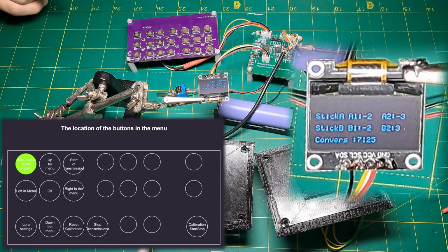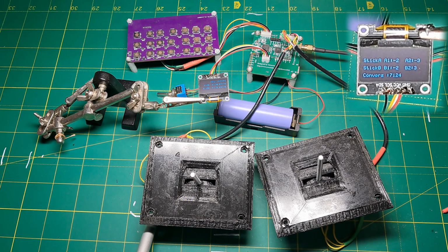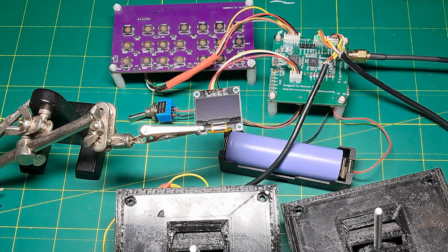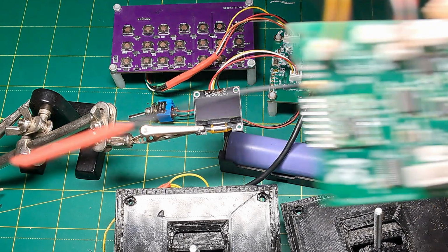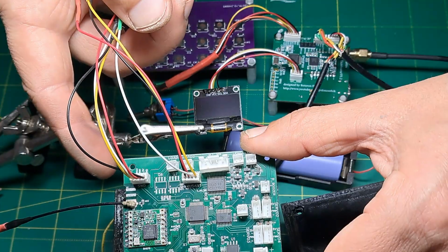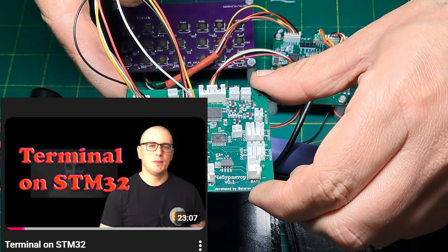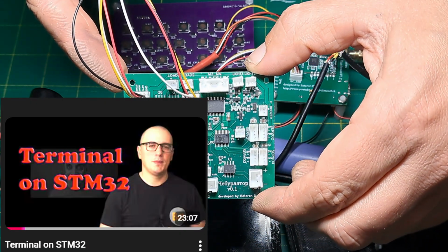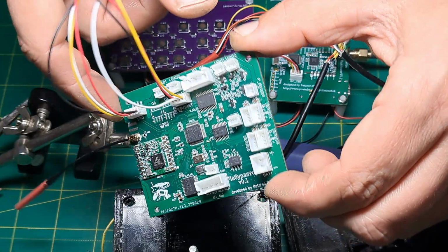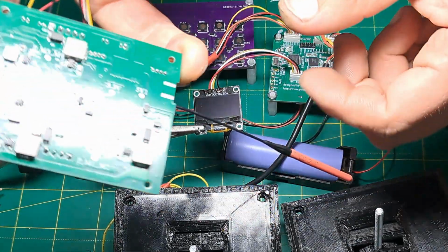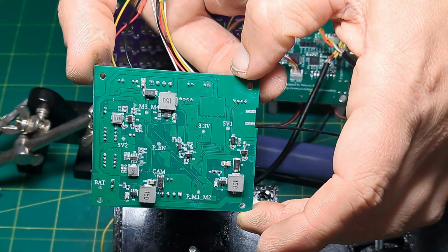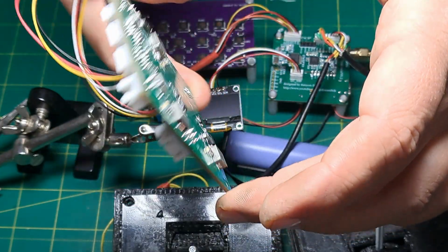I'll click the ADC conversion display button. Now you can see the numbers changing on the screen, which means the sticks are working. You can also see the number of conversions: 1123 conversions per second. We will be using this receiver, and I'll also be posting the firmware on GitHub. In one of our previous videos, we wrote a command interface for it. I added another command to the command interface and several functions for outputting received LoRa commands. You can explore this in the source code.